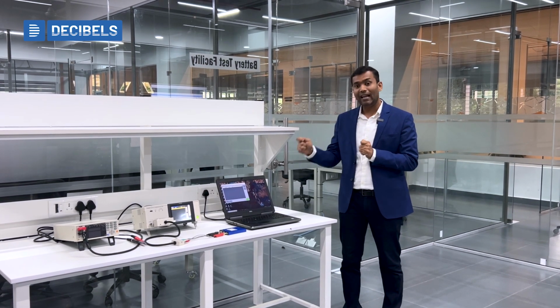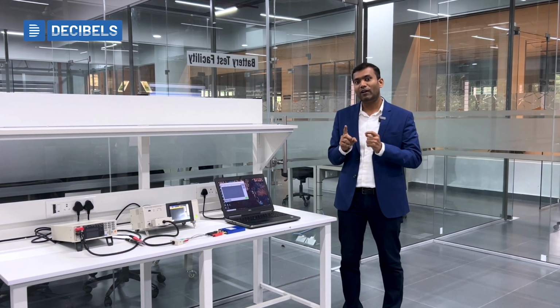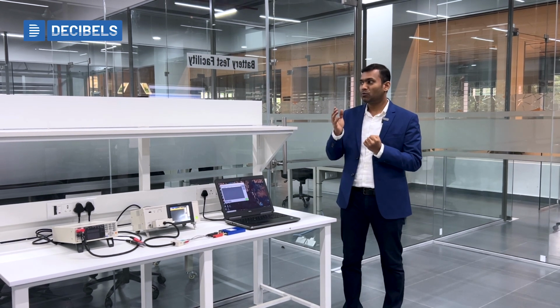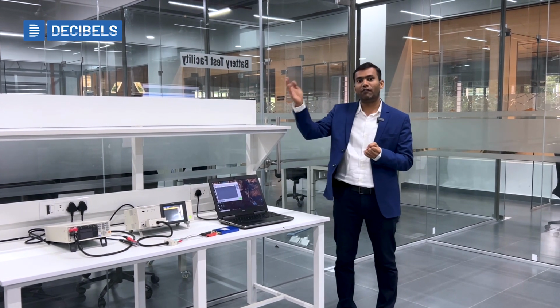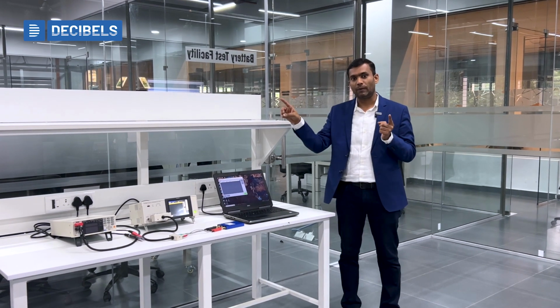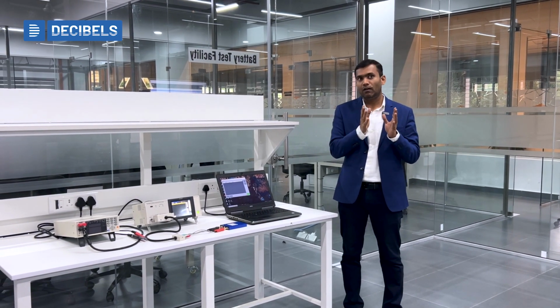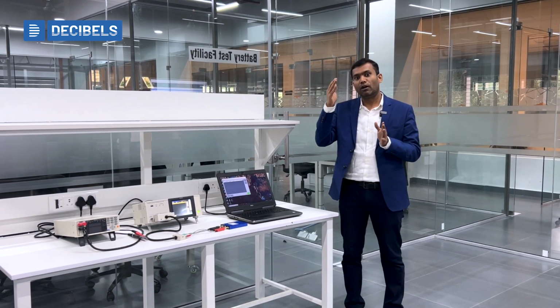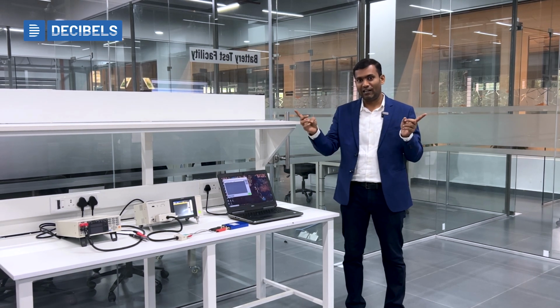But the criticality of these machines, which are specific to testing lithium-ion cells, lies in two critical parameters. One is the frequency range, that means the lowest to the highest frequency we can sweep, because to understand the behavior, we need to sweep the frequency. Typically 1 millihertz to about 200 kilohertz is the required range.